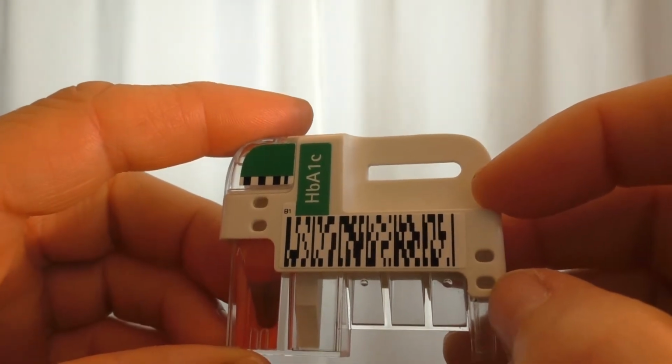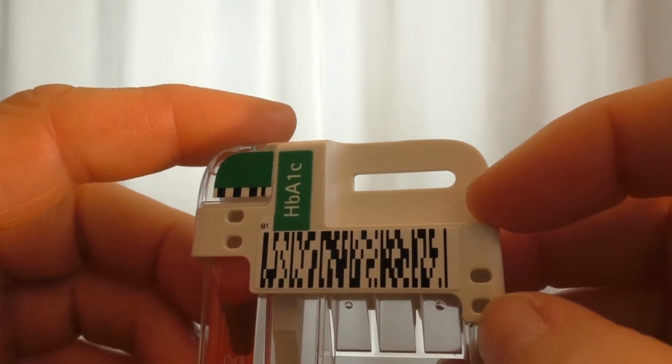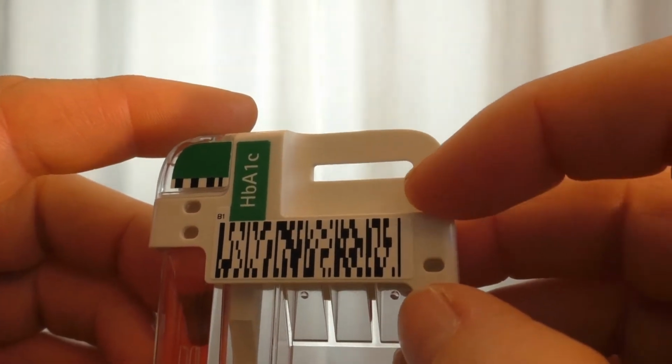This means that the machine that is going to place the label needs to be both accurate and precise in order to prevent bad parts. If you have a machine that needs to be both precise and accurate, like this one, you could risk having a lot of scrap. And if this is the case, usually operators and technicians want to do a really good job, so they start adjusting the machine. And does it really help? Not necessarily, because if your problem is precision, then you can't adjust out of the problem.